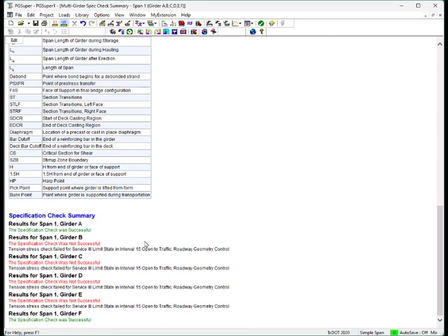Oh no. Now it appears that we've increased our haunch depth, and this has caused more dead load and is causing our service 3 limit state tension at final to fail. Oh, we have some work to do here.